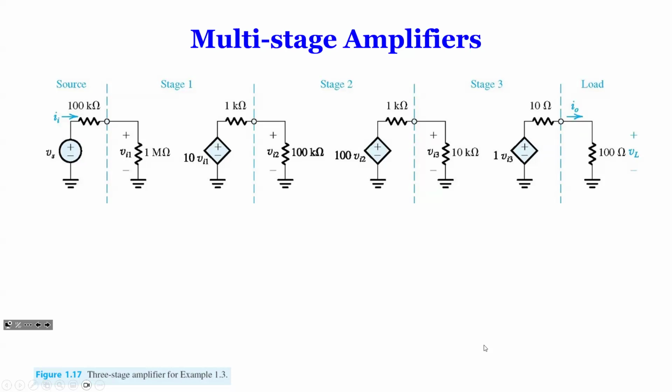So you amplify another one, and this is 100 times this one, and with 3, and then the last stage only amplifies 1. Again, you might say, why just amplify 1? Well, because we want to make sure the output resistance is small, 10 ohms. Do you see that? But this one has an output resistance of 1K, right? So 1K is too big. So we add another stage, not to amplify the voltage, but to reduce the output resistance.